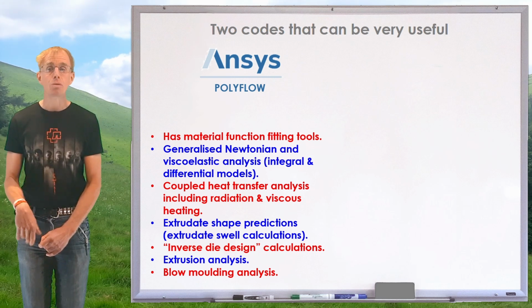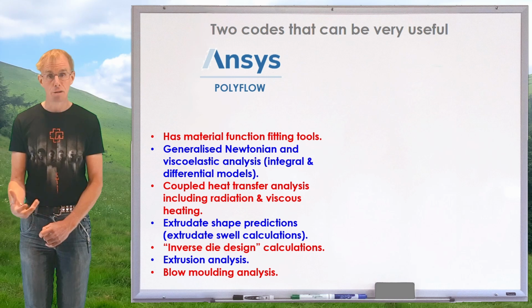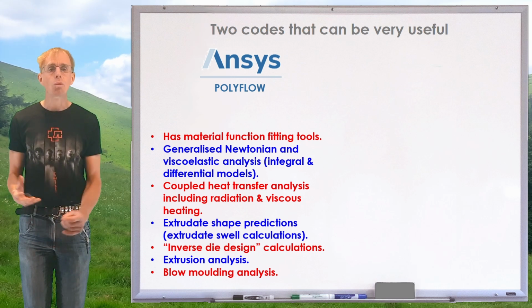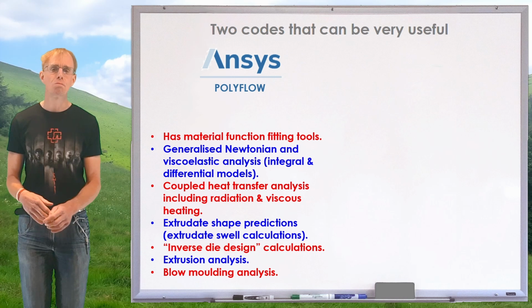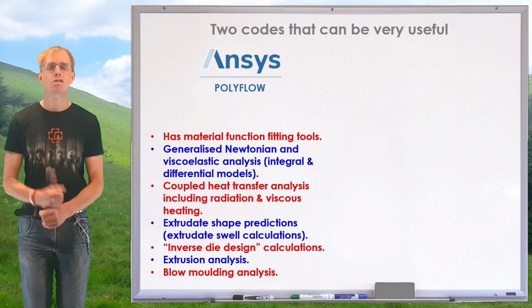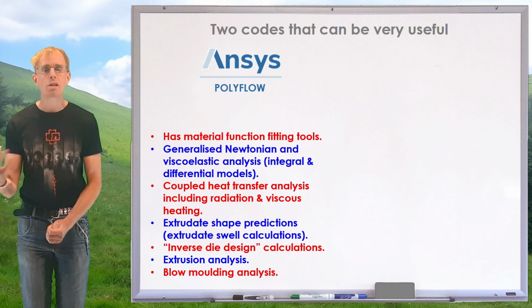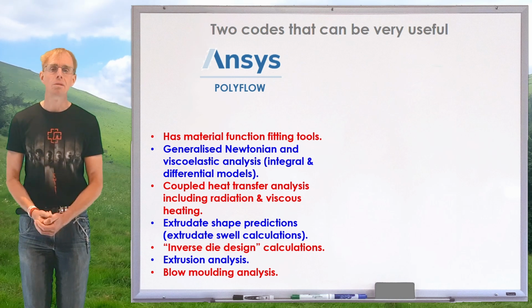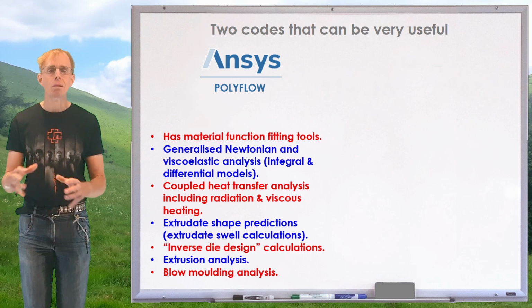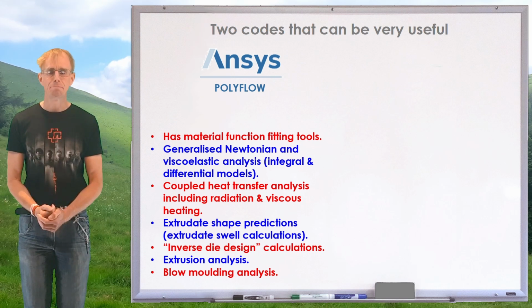It also allows you to couple heat transfer, including radiative heat transfer, and also heat source terms. So for example, you can approach problems where you have a generalized Newtonian fluid with a specified temperature functionality, including viscous dissipation, which is a topic we're going to be talking about in depth later on in this course, and it will be able to give you a flow simulation for that.